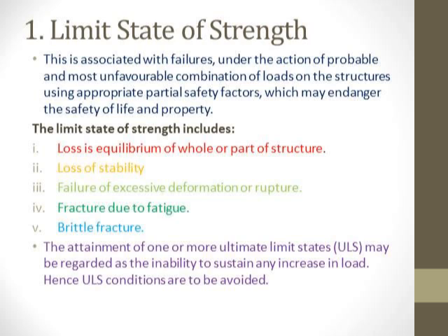Loss of equilibrium of the whole or part of the structure, loss of stability, failure by excessive deformation, or fracture due to fatigue and brittle fracture. These are the points which have to be included in the limit state of the design.